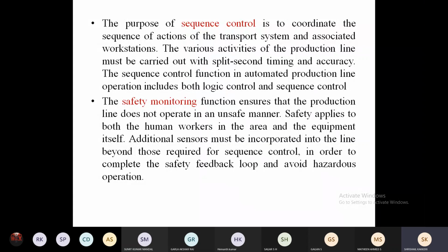So these safety monitoring devices will often be provided within the work line and at a specific location of the work line. For example, a robot will be controlled with three main safety monitoring systems. There will be sensors on the robot, sensors around the working station, that is the work volume of the robot, and sensors beyond the work volume of the robot. These are the tertiary level, secondary level, and primary level of sensors.